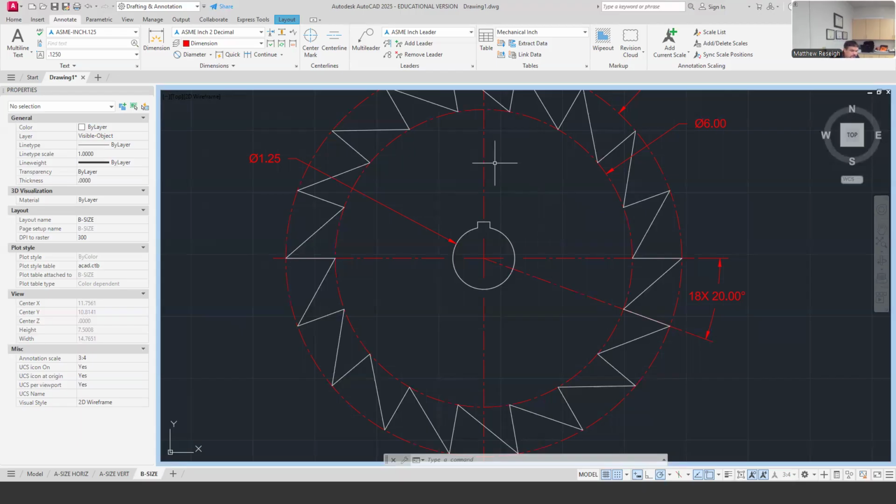But even in 2023, I saw companies still getting things wrong that you think they should have dialed in, like keyways, key seat, and key size. There was some equipment that was built that was just kind of scaled up to fit. We took some old models and said, oh, they just need to be about twice as big to handle twice as much load. And the truth is that didn't work out.